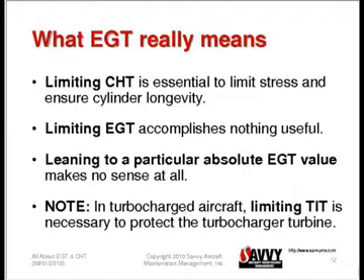On the other hand, limiting EGT accomplishes nothing particularly useful, because high EGT does not mean that the engine is under stress. In fact, most of the time, it means the opposite. Most of the things that cause EGT to be elevated are things that actually cause the engine to produce less power and to be under less stress.